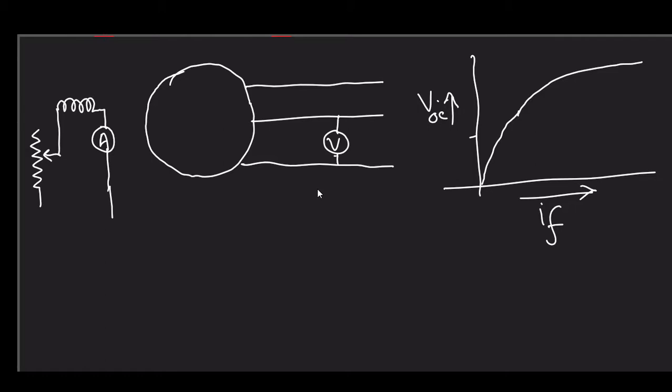Therefore if we increase H beyond our linear region of operation, the change in B is not proportional to H. However, our induced EMF is proportional to flux, which is directly proportional to B. So whatever variation we observe in our BH curve, a similar variation we can expect in our synchronous generator output characteristics curve.